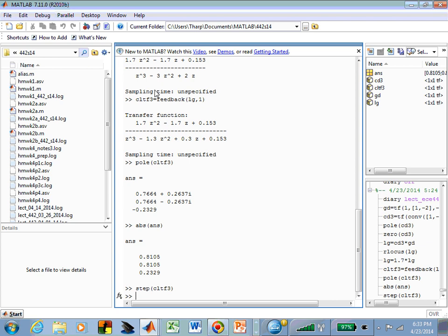It may not have quite the overshoot because I think this one wouldn't be as demanding, because you're not trying to squeeze it down towards the real axis as quickly and as abruptly as you were with 0.9 plus and minus j0.1. Now you're maybe being more gradual with bending that over. And the other thing is maybe your zero would slide a little bit to the left of Z equal 1.